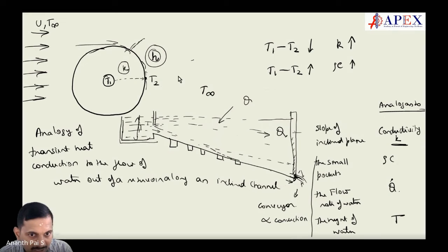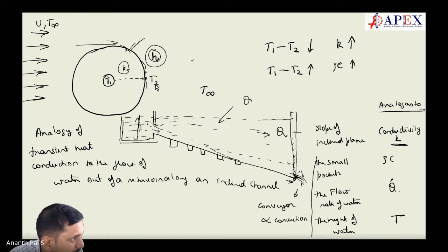So as convection heat transfer goes, T1 is equal to T1 and it is dropping with the time. This kind of analysis or assumption is called lumped mass analysis, where you take the whole temperature to be the same. Clear? Have you heard about lumped mass analysis? You can consider the whole mass having the same temperature.